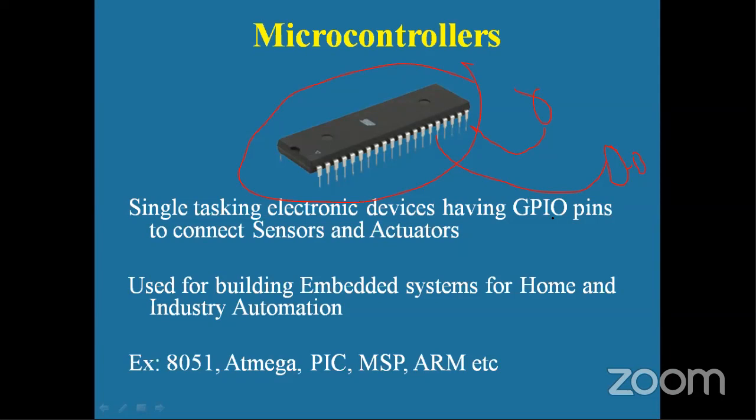But the most commonly used microcontrollers are the 8051 microcontroller, then the PIC microcontroller, then MSP, ARM, and this also completely depends upon your requirement. If my requirement is not much, a very simple application, then I go for an 8051 based microcontroller. If it is real time, then I go for PIC. Industries use PIC. Then you have ARM processors for much more powerful work, with a lot of GPIO pins and all that. Okay, let us go further.